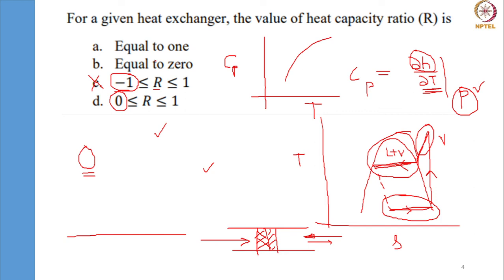But a word of caution: if you take Cp of a particular fluid at higher pressure and Cp of the same fluid at a lower pressure and lower temperature, you cannot compare the Cps. But if they are at the same pressure, Cp of hot fluid is greater than Cp of cold fluid.